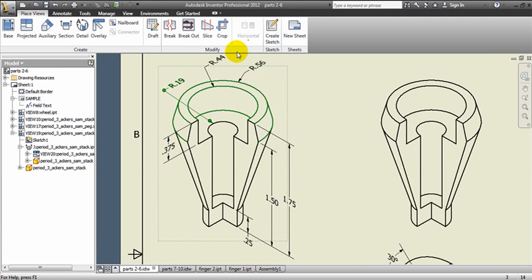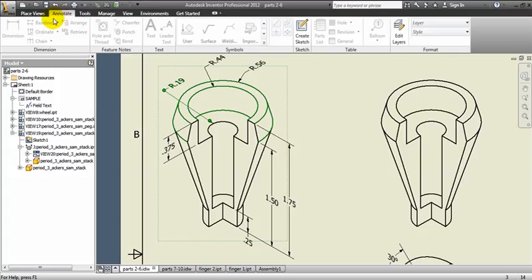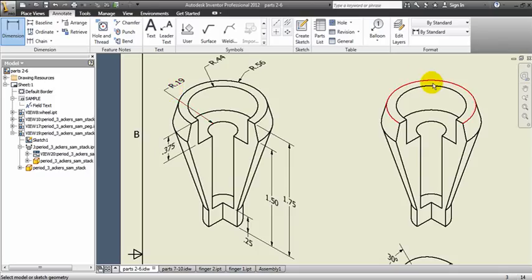Alright, now we're going to put these dimensions on them, and you dimension this just like you do normally, but sometimes a little differently. So I'm just going to go through this just to make sure everyone's on the same page. I'm going to put all the height dimensions on the right and all the radius dimensions on the left, or diameters, whatever. Go to annotate, hit your dimension, and I'm just going to dimension all these circles first of all.